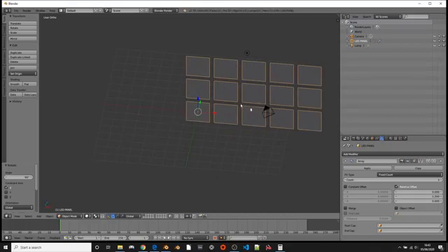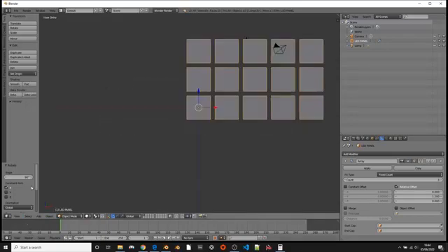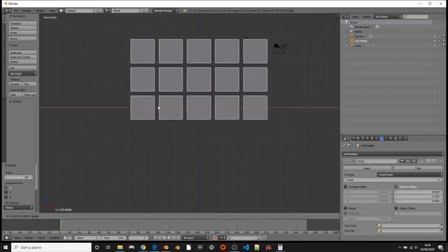Now I want to get it centered as well, just to my world, just because I'm fussy like that. So let's do a front view like that. There we go. Basically what I'm looking for is this crossover of the blue, which is my Y, well, it's the Z in Blender, but it's my Y, and my red, which is my X. And I'm going to just use the handles and move this object roughly until I'm there.